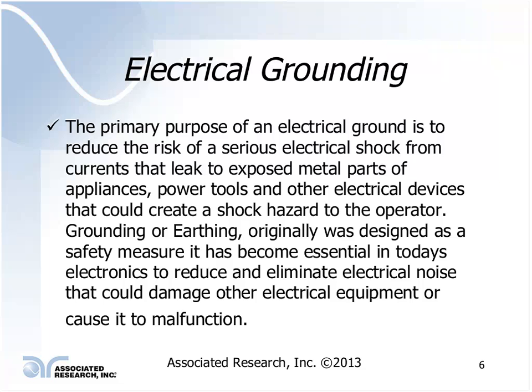There could be enough leakage current within the product going to the enclosure of that product that could create a shock hazard. Grounding or earthing is one method of safely routing that leakage current back to earth and guarding you against an electrical shock hazard itself.